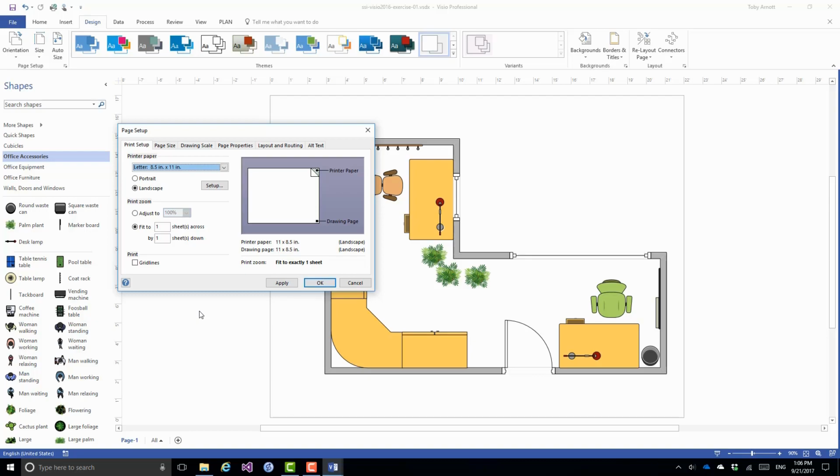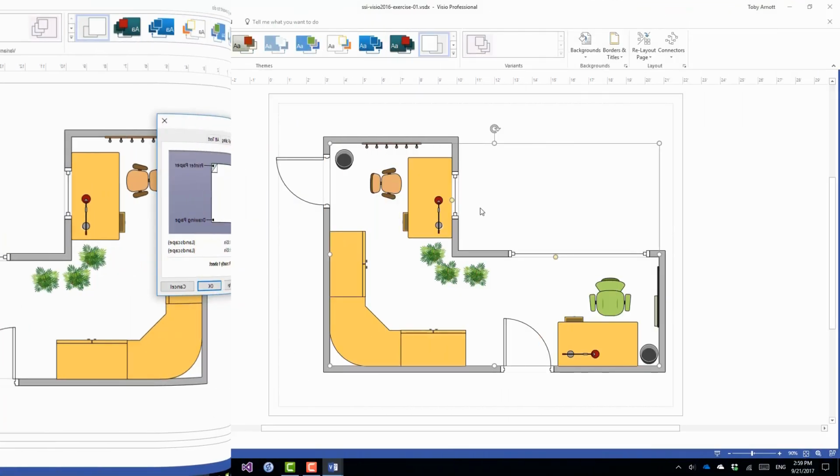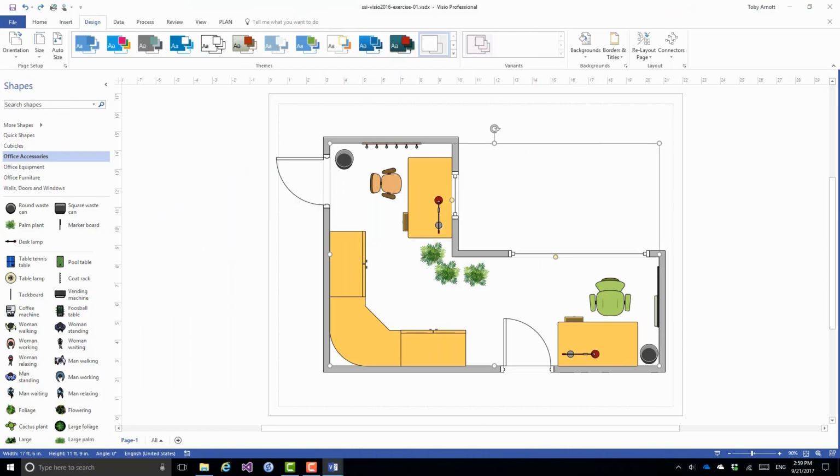Similarly, I could take a drawing with a very large page size and print it on very small paper by scaling it down at the stage of printing it. So the page size and the print size in this case by default are the same, but using the Print Setup facility I can rescale what I'm doing to print to whatever scale that I want. Now, as I mentioned a couple of times there, we're going to be looking at printing in more detail later on. But for the moment, let me just give you a quick demonstration of what I've just been talking about.